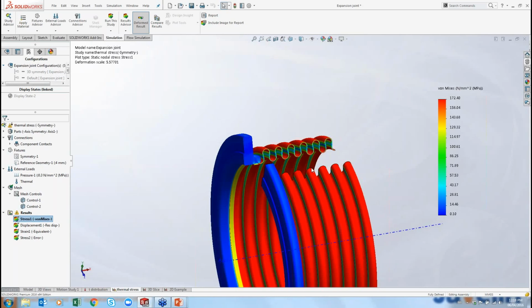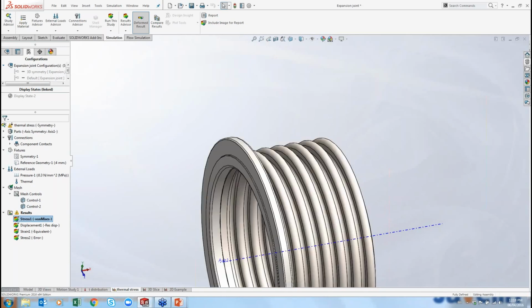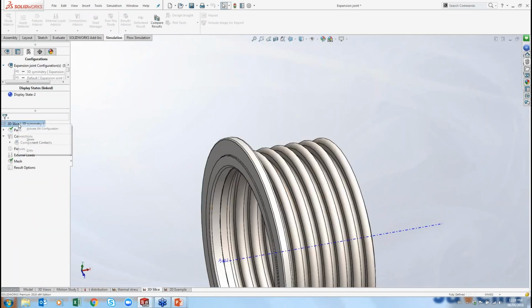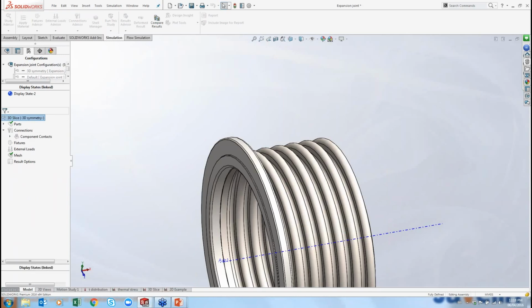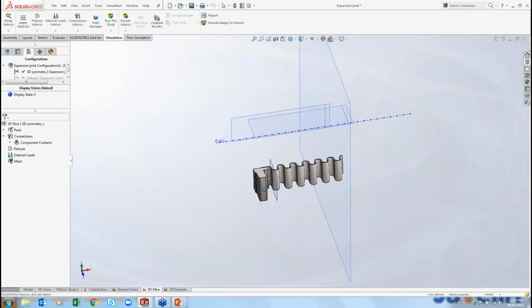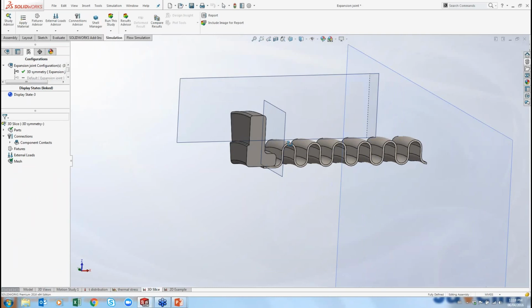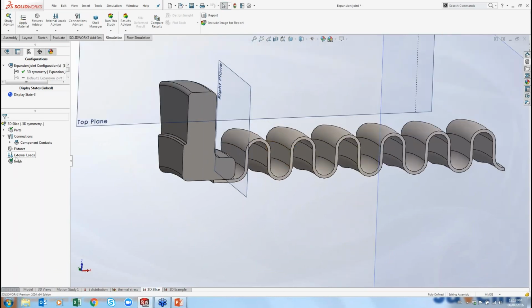Now, I'll show you guys a little bit more about why we couldn't do this in 3D, and again, it comes down to sort of element overload. I'm going to look at just a 3D slice of this model, guys, just a very, very small slice of it. There we go, this one right here. And if I use the same mesh settings on this that I did for the 2D model, to get the same number of elements going through the thickness, let's see what that mesh looks like.